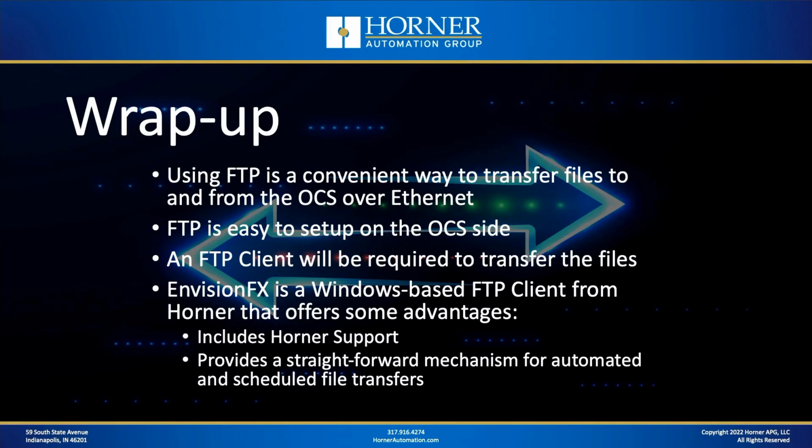Our technical wrap-up is as follows. Using FTP is a convenient way to transfer files to and from the OCS over Ethernet. It's super easy to set up on the OCS side, just a couple of steps. You will need FTP client software of some kind to transfer the files. EnvisionFX is an option if you're using an OCS on a Windows-based PC, of course. And the advantages of EnvisionFX is that you get Horner support, and you have a straightforward mechanism for automating and scheduling file transfers.